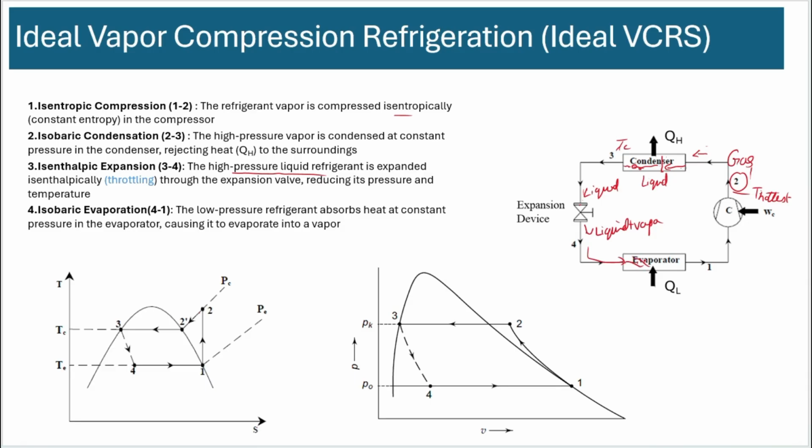The remaining liquid evaporates, and by the time it reaches here, it's all vapor again. Okay, so it's vapor here and goes to the compressor. So this way we solve the practical issue of compressing a liquid or a liquid vapor mixture by putting the compressor here, and also solve the issue of having two compressors by compressing it to a higher temperature and dropping it in temperature, and then expanding it later through a throttling device.